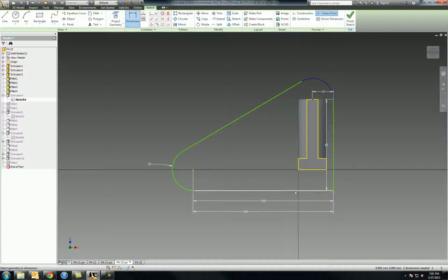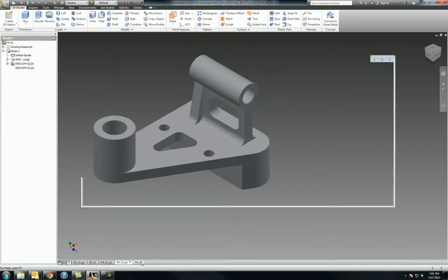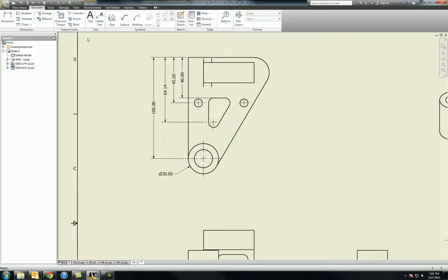If you notice all the green geometry that exists here, that says it's not fully constrained. What that means is that I'm going to have problems with this the entire time. Now I've got 30, I can go to my hole and thread note, dimension that, a diameter of 18 through hole.